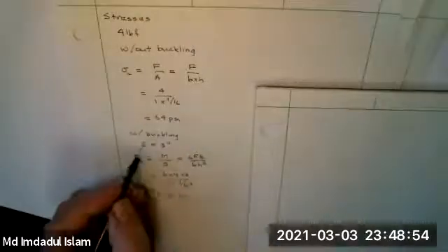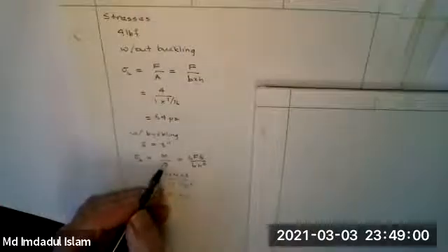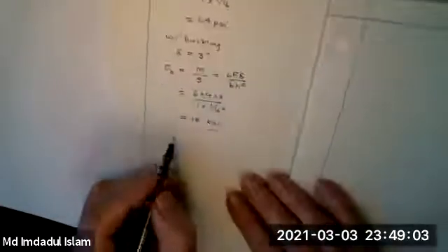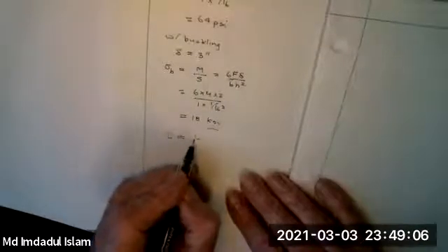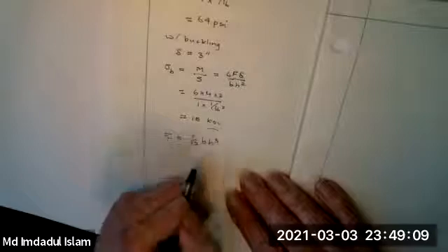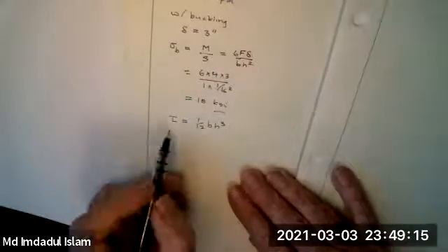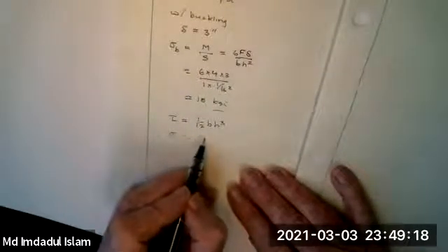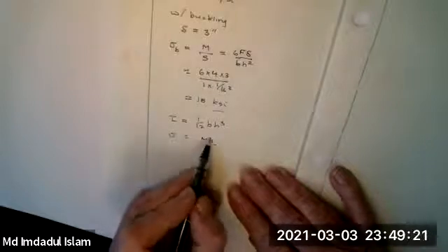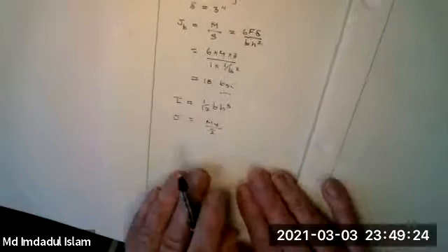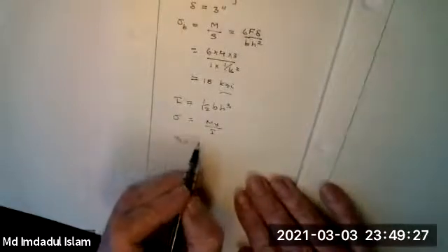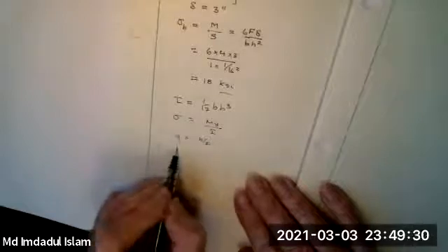What's the S at the bottom? Sorry? What is the S at the bottom? The S there? Down. One. Up, up. S is the section modulus. Sorry. So that's I. And when you go get your bending stresses, when you make Y as big as possible, that'll be Y equals H upon 2. So this will become